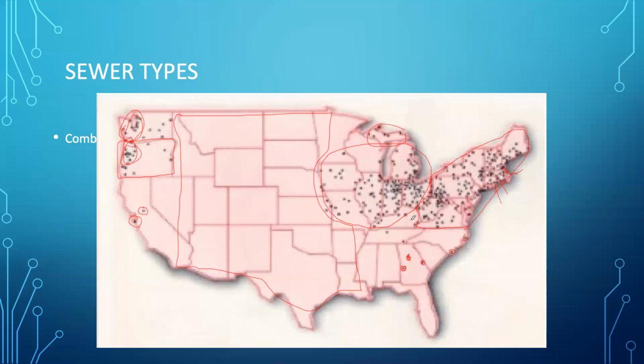And the real challenge, the hydraulics of that is not going to be all that hard unless you're out of a pipe. But the challenge is we design our treatment plants for, say, 100,000 people that are eating food and creating wastewater. And then all of a sudden we have this huge stormwater flow that comes into the plant.